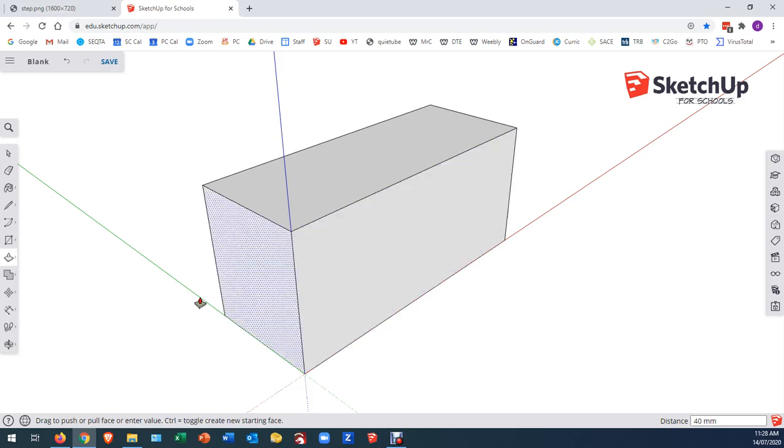Okay, and just to demonstrate that, I can put up my dimensions here. My dimension tool is this one over here, and I can pick dimensions and go from endpoint to endpoint. You'll see that it snaps to the end, and then it snaps to the end, and I pull it out and it says 90 millimeters. SketchUp works with snapping in a number of different ways. End to end is a common one. So you can see my basic dimensions are correct.